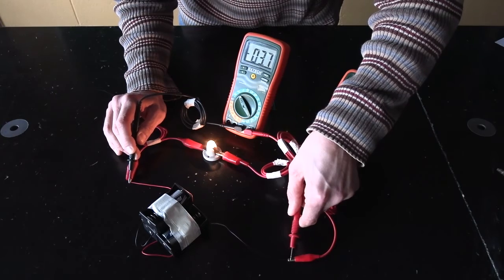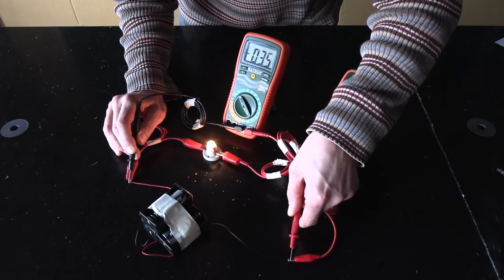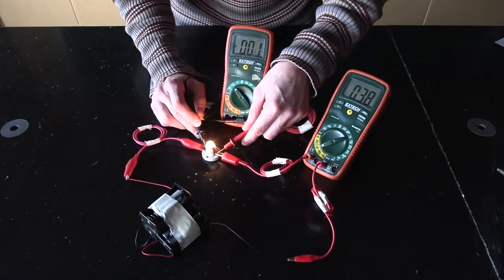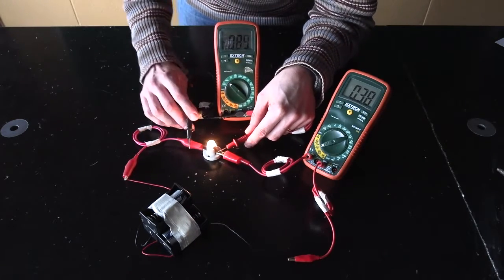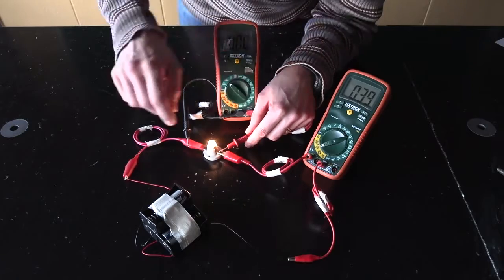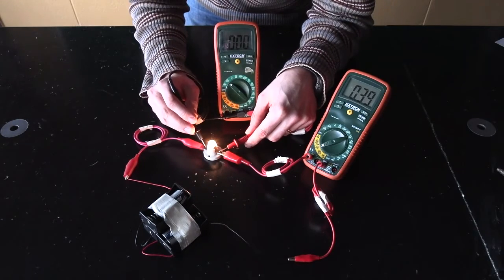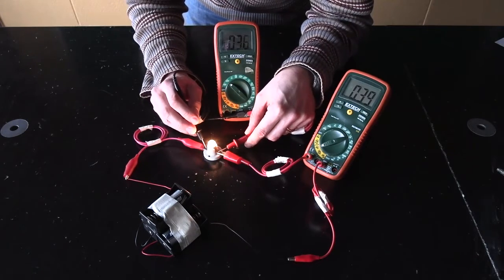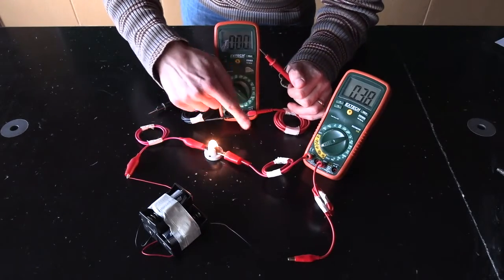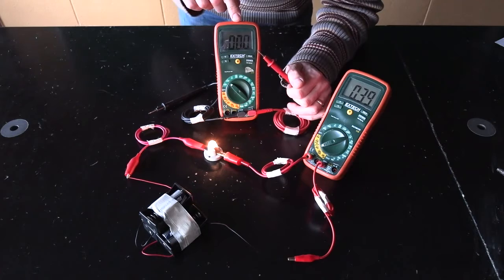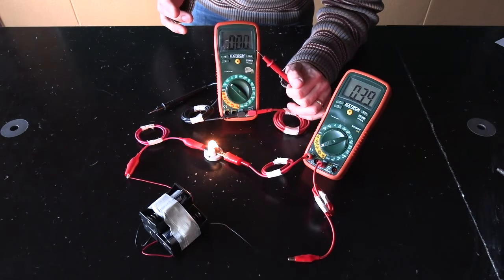And I get the same thing, approximately 3.7 volts. So since it's in parallel, what that means is that the resistance here had to be low because it was in series. Here, since it's in parallel, we don't want any of the current to skip the light bulb and go through the voltmeter instead. That would change the circuit.